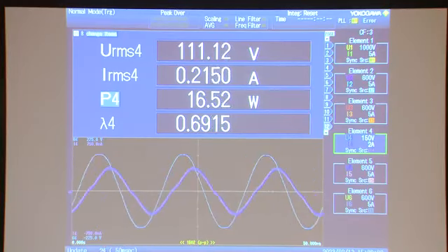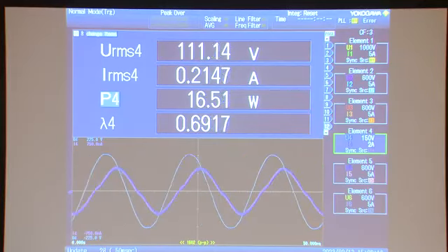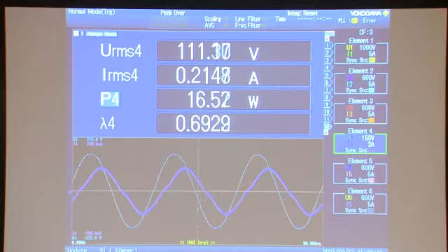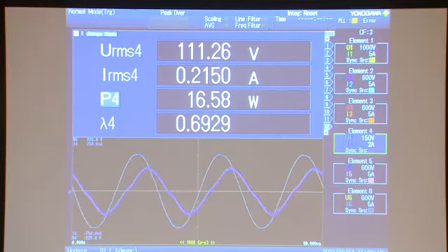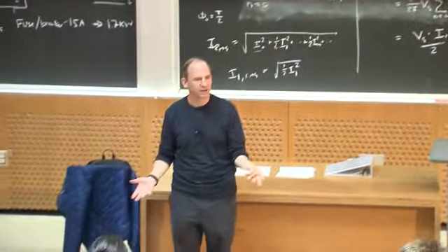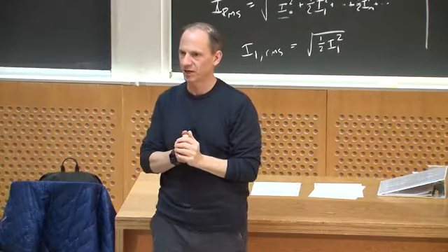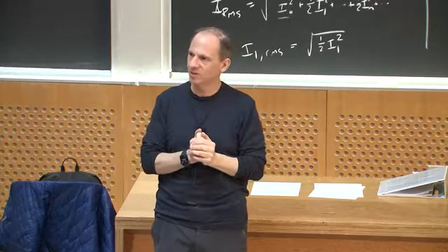So people are asking, well, what if you're a big industrial user, right? A lot of big industrial companies have lots of motor loads, the pumps and whatever have you that they're driving, right? And that tends to generate an inductively loaded power factor. Okay, so this isn't so much the distortion factor, this is displacement factor.